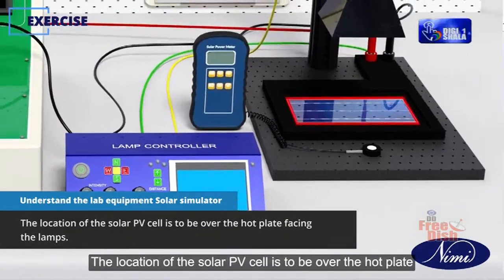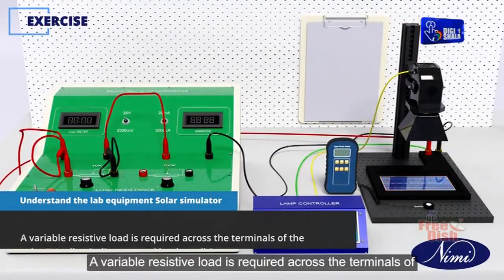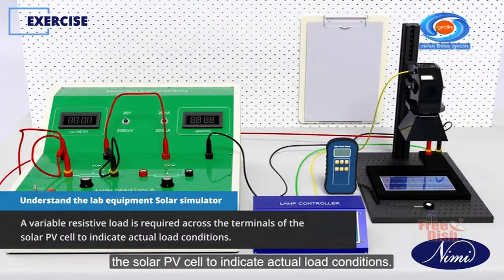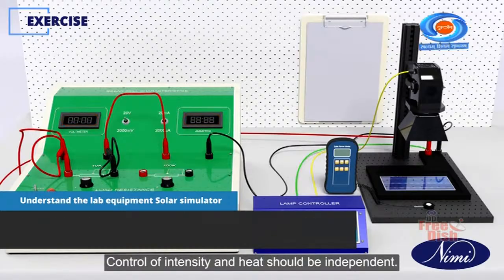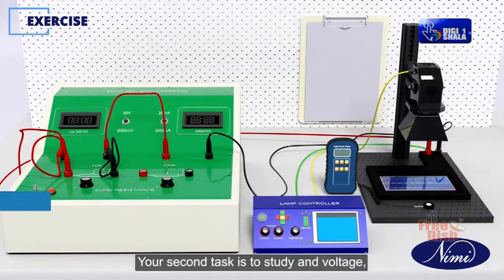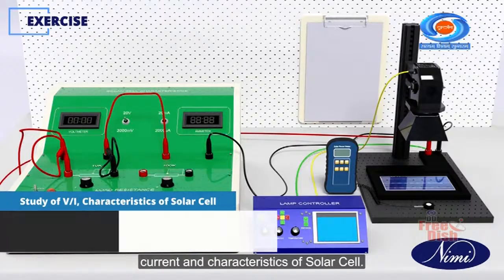The location of the solar PV cell is to be over the hot plate facing the lamps. A variable resistive load is required across the terminals of the solar PV cell to indicate actual load conditions. A set of digital, preferably voltmeter and ammeter, are essential on front side. Control of intensity and heat should be independent. Your second task is to study voltage, current and characteristics of solar cell.